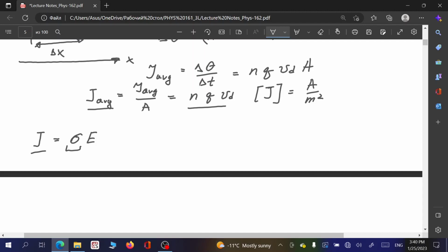So actually, it's silver. Gold is quite close and commonly used in electric circuits because of its inertness, so it doesn't oxidize and doesn't change its properties over time. Specifically when you have a mechanical contact between two conductors, you don't want the contact to be oxidized, because then there will be no contact.